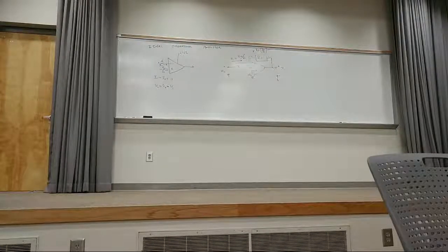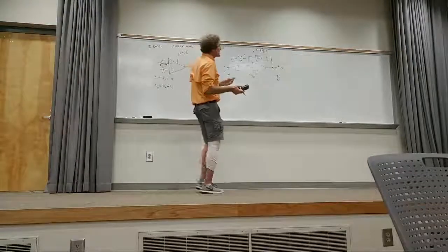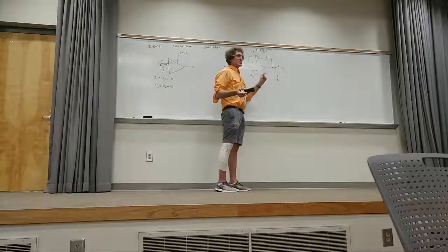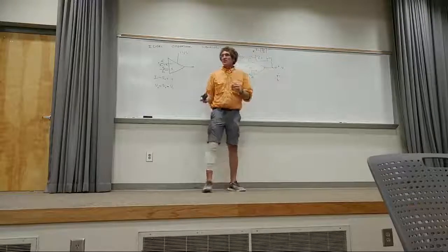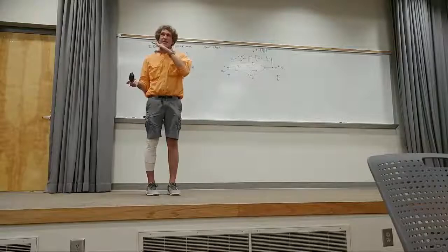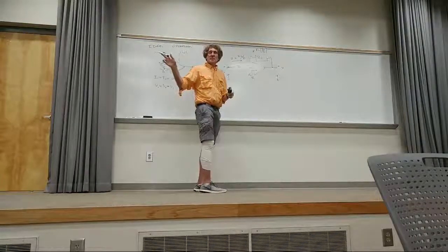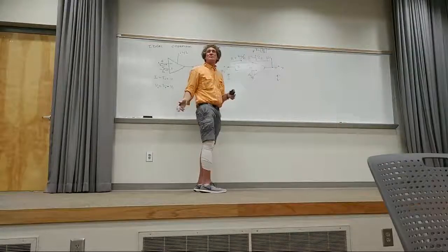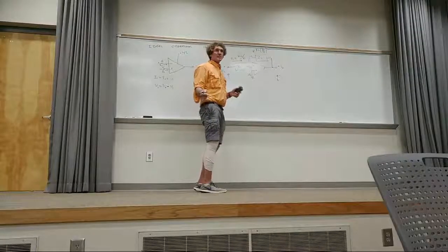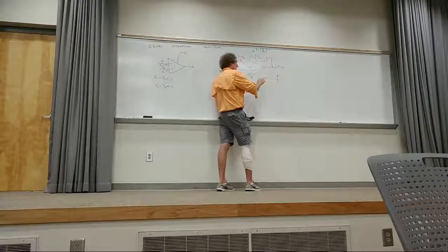It's something very simple. Now, if you see that, what is the voltage between the plus and minus terminal here? And I want to make sure I show you this, because kids make this mistake routinely, and I think it's because they're not careful. The way I always tell kids, anybody, any student, undergraduate, graduate, high school, doesn't matter. If you want the voltage between 2 points, you start at the negative terminal, and you go around. So I'm going to go from here to this point, still 0 volts.